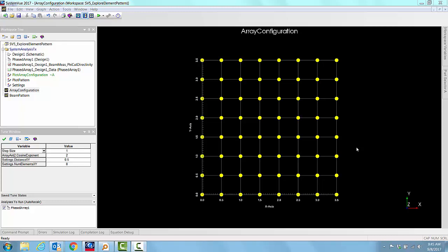In this section, we will examine how we can make the antenna element model more realistic so that our phased array architecture represents close to reality. Let's take the case of a 64 element phased array arrangement, with each one of these elements modeled as isotropic. Isotropic is the easiest and quickest to assume, and also a good first order approximation for an antenna model.